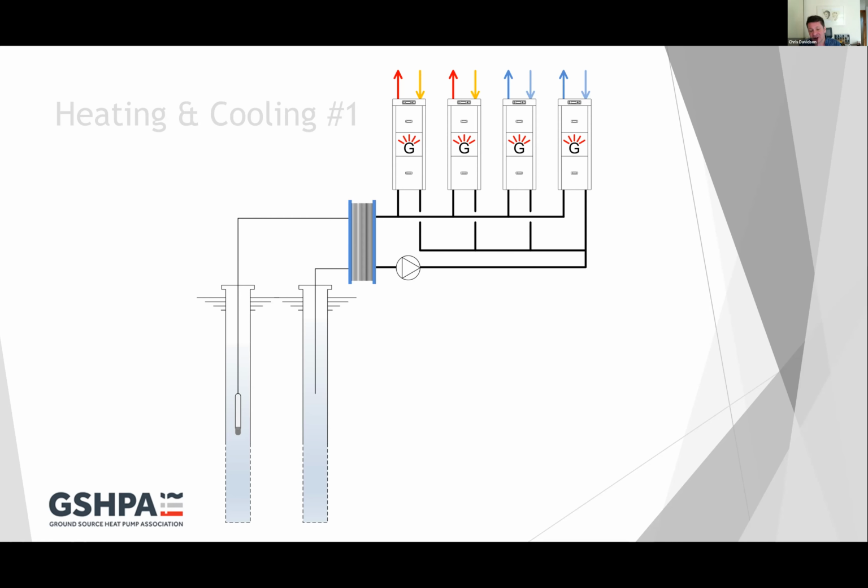So rather than trying to control what this water temperature is, we know what this system is going to be delivering. And so we actually design in those limits that are required by the Environment Agency. But it keeps it tremendously more simple by just monitoring this temperature for a high limit and a low limit, and then running the pump down the well to maintain that within a bound that we are happy with in the system.